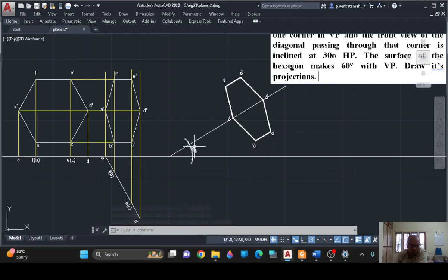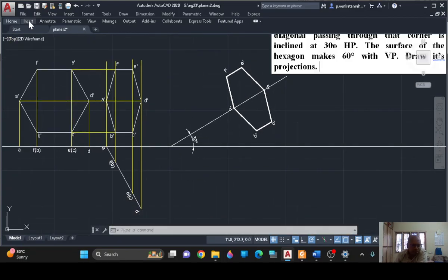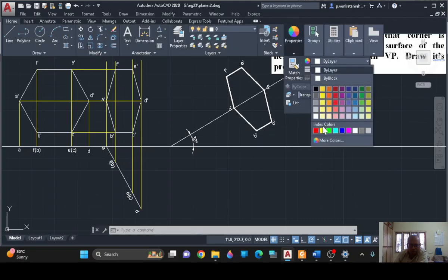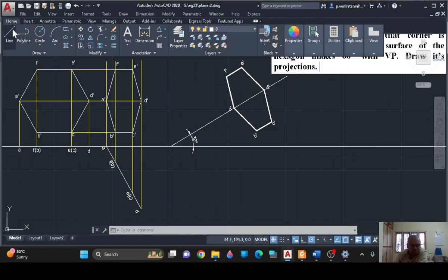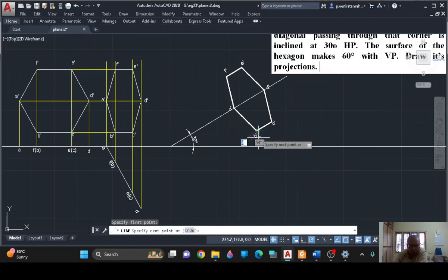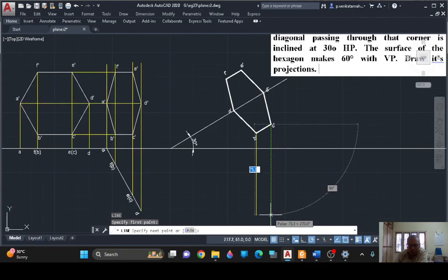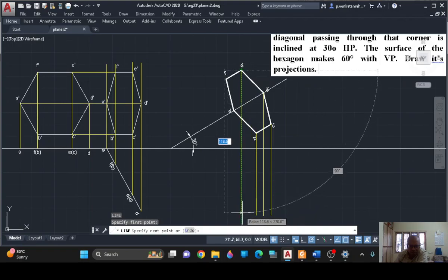So the next step is I have to draw the projections here. So from this I have to draw the projection here. From B dash I got a projection. Now I will get a projection from C dash and I will get a projection from D dash. I should not leave any of these points. So better is to give the names first and then draw the projection from this.